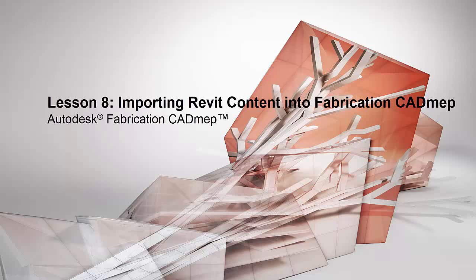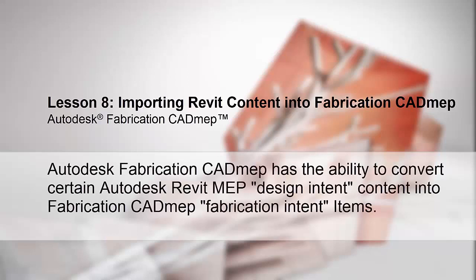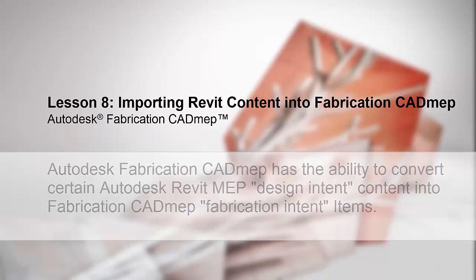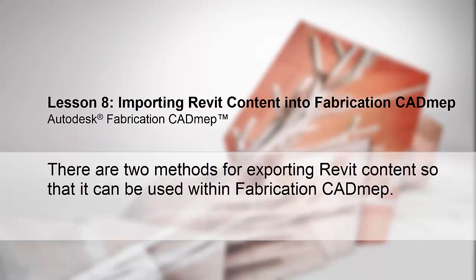Lesson 8, Importing Revit Content into CADmep. Autodesk Fabrication CADmep has the ability to convert certain Autodesk Revit MEP design intent content into Fabrication CADmep fabrication intent items. Leveraging design information created in Revit can greatly increase productivity by reducing the time and effort needed to create detailed fabrication drawings. There are two methods for exporting Revit content so that it can be used within CADmep.